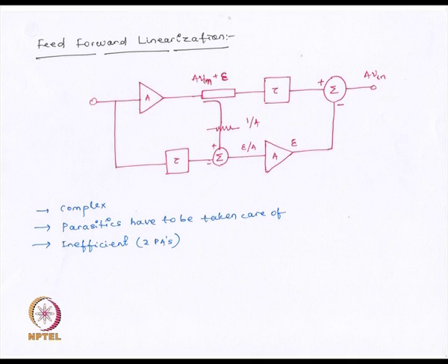So what we get at the output is epsilon, that is the error factor again, and now if we again subtract it from this signal after proper delays, then we can get back the correctly amplified version of the input with no non-linearities present. Ideally no non-linearity should be present, but in practice some non-linearity is always present.